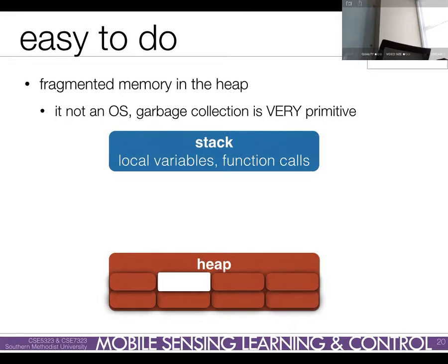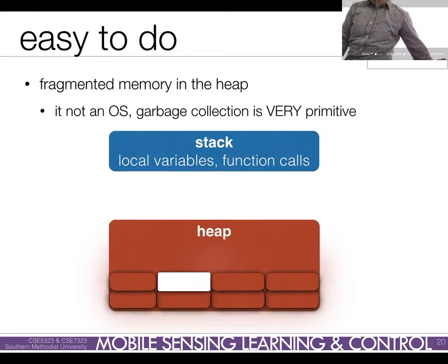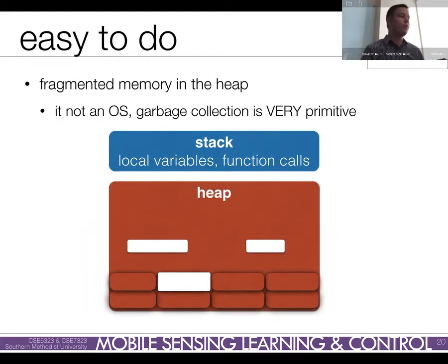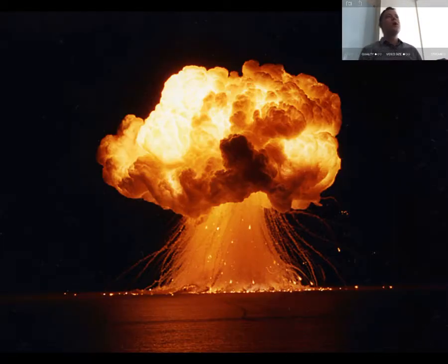So the next time you want to allocate memory, it stacks it on the top. And then maybe you do some more deallocations in here, and you keep allocating some more memory. Maybe you're really deallocating, like you don't have 2 kilobytes allocated in the heap at all. You do this. Then what happens? Boom. It will only free up that memory if everything that you allocated after that, you also deallocate. Then it can start taking the heap size down. So if your heap is fragmented in any way, it'll blow up, metaphorically.